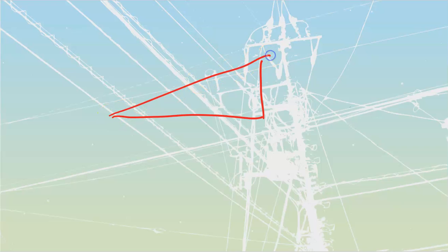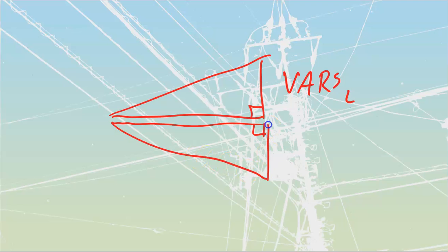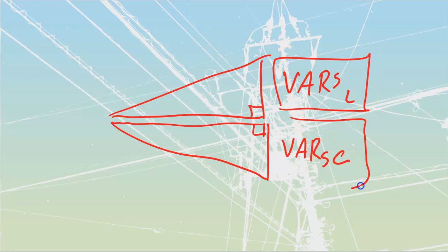The convention for power triangles is if it is going to be a vars L type of triangle, I'm going to draw that triangle to the top, like that. And if it's going to be a vars C triangle, I would draw that triangle down to the bottom. So, that would be my vars C. Direction is not going to be important to us, as long as wherever we draw our vars L, we draw our vars C in opposition to them, so that we can get to the next of whatever we're going to have.